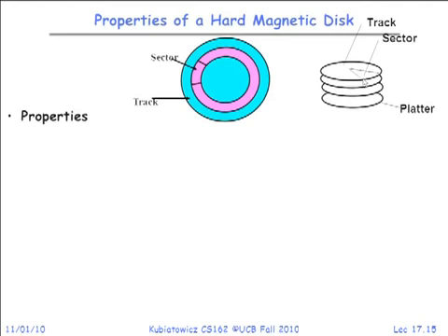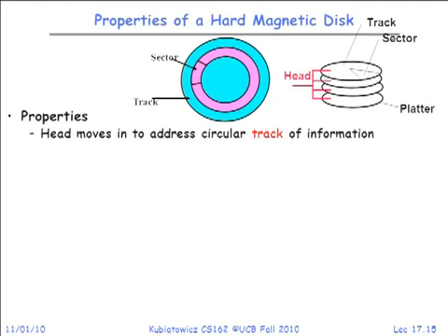So the head moves in and out in tandem. Typically, if you've got multiple platters and multiple heads, they all move together. It's not like you can have individual heads and different platters move in different ways. Does anybody know why that is? If you look here, see how these heads are tied together with a single stepper motor. So all N of the heads move together.